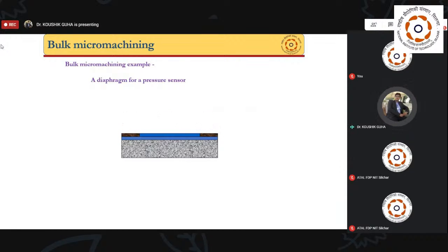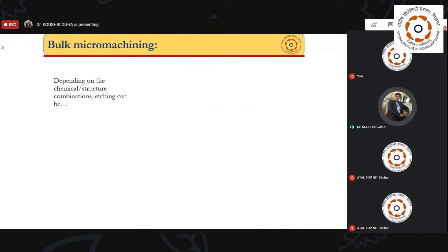Now the unexposed region will be developed, and this unexposed photoresist will be removed by the developer solution. Then you can etch the SiO2 layer with an HF solution. After that, we also remove the remaining photoresist. Then you can etch the silicon substrate with KOH solution. So this is bulk micromachining, where the bulk part of the substrate is being cut away.